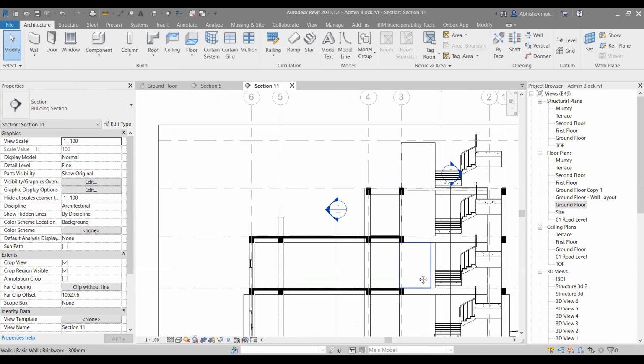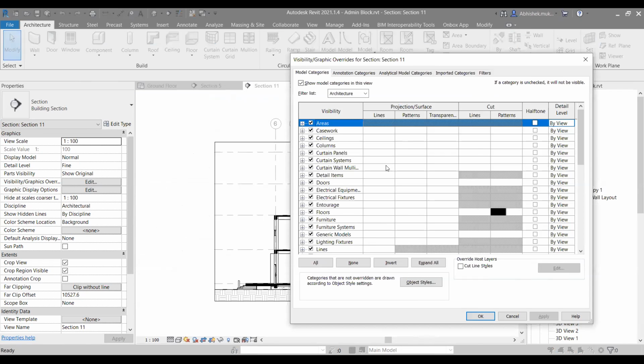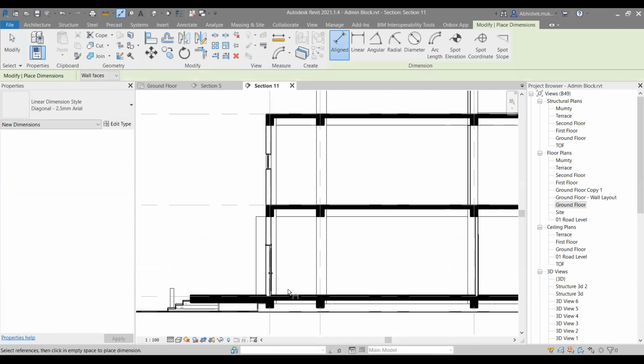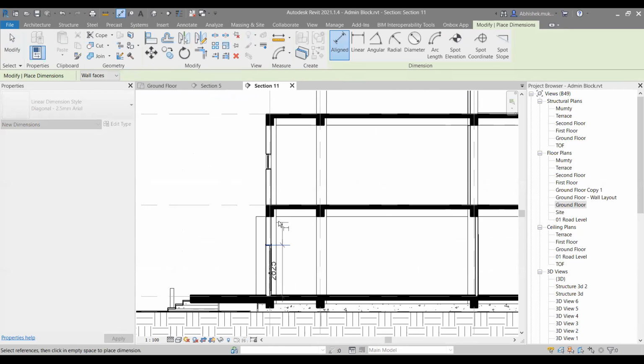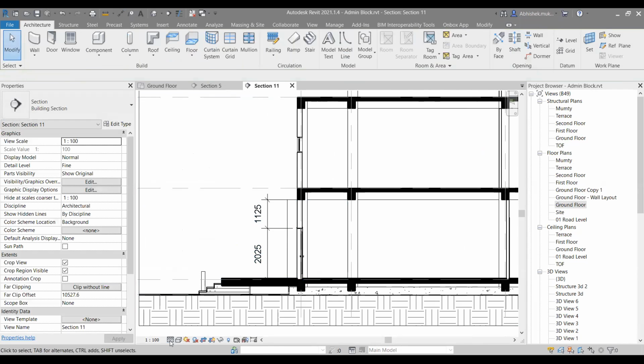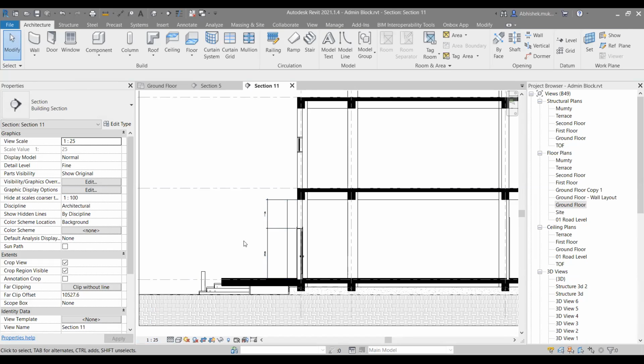And it's that easy to actually make the section look good. Oh, the section line should also be, let's say, half tone, or I can also switch off the sections. And then later on, I can just do dimensioning. Just the same continuous dimension which we used to have. And the dimensions and text, everything over here in Revit, are annotative. That means if I change the scale, of course it isn't 1:1, but if I change the scale which I need for the printout, then you see that these are also reducing. They tend to be readable.